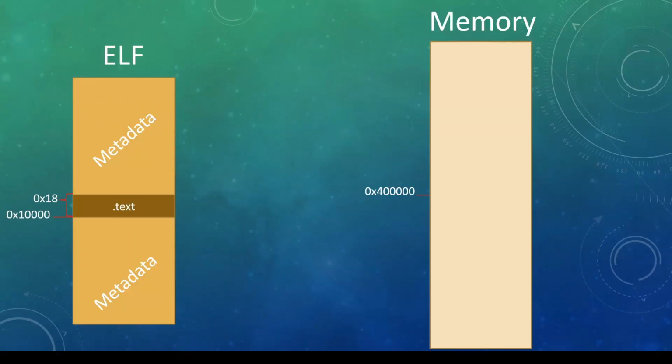But in embedded systems, many times we do not want the entire ELF on very limited storage, and we don't want a loader, so we just do everything beforehand and store just the binary on our storage and then run it when the time comes. Let's see how we can take out just the part that we need, just the .text section, and then what we are left with. So the flow on bare bone embedded systems is going to be to first get the bin from the ELF, and then we can store just that bin. We do not need to store the entire ELF, nor do we want to.